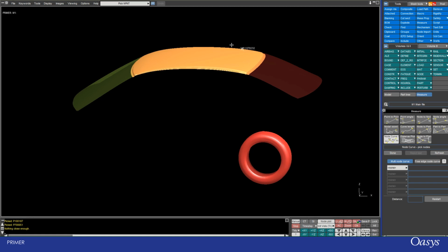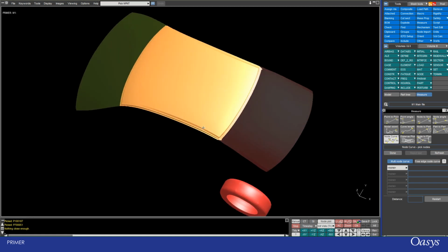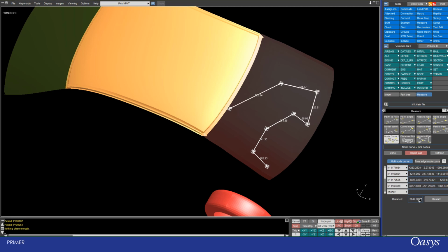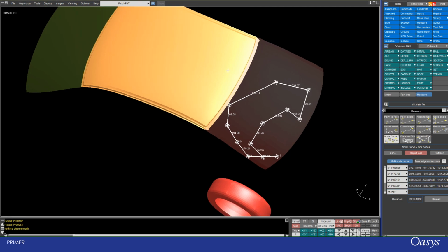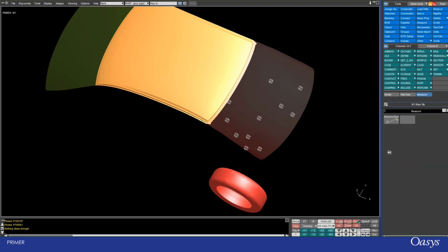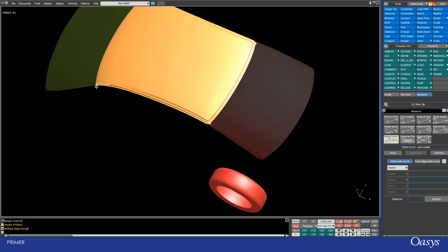Then you might want to trace a curve with selecting nodes and measure the total distance of that. So this is the sort of free-form clicking. So I can just click around, and as I click, notice the node list is growing and the distance is also increasing. So now we're about 3 meters there. That could be useful if I make a mistake, I can reject last and click again. If I click done, then that finishes that, and I can click on the option again and do it again.